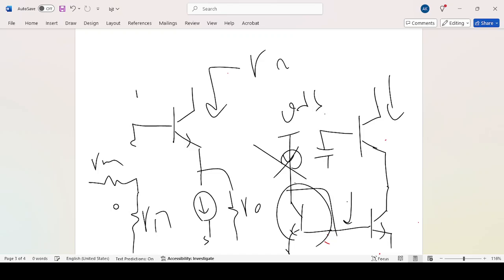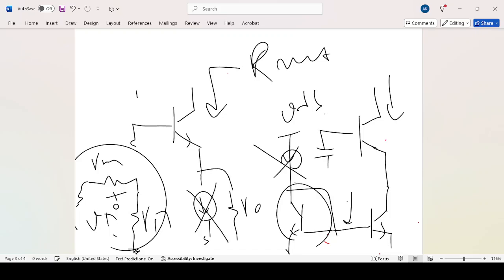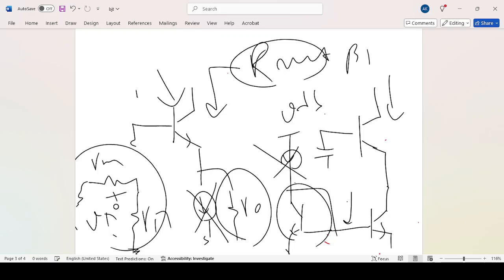So the R out here is, but you see that because both sides of this part are terminated by ground, you do not have V pi here, so you do not have a current that flows through this transistor to reduce the R out. You only have the R out. This is why you have beta RO.